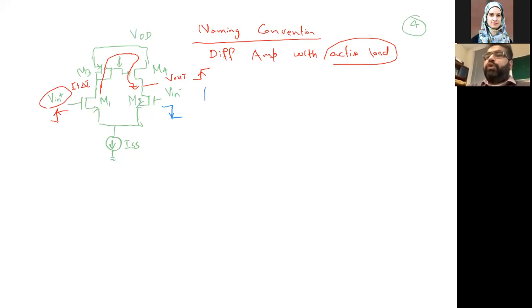And please make sure to understand, pause the video, go back, make sure to clear this point, because that is very much important, that both of these trends are ultimately increasing the V out. From M1, M3, and M4, a positive increase is coming, a non-inverting behavior is coming, whereas from the M2, an inverting behavior is coming. And ultimately, both of them will make your V out high. So ultimately enhancing the gain because of these two loops.